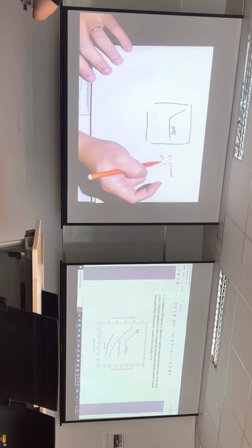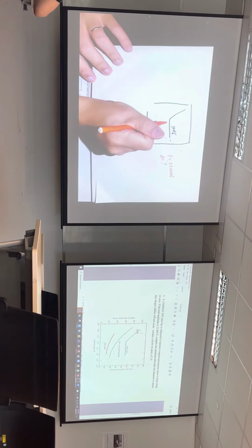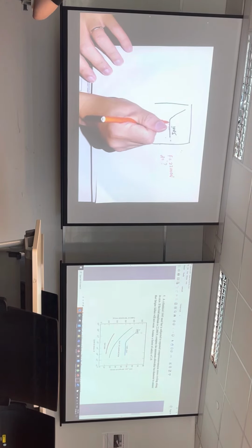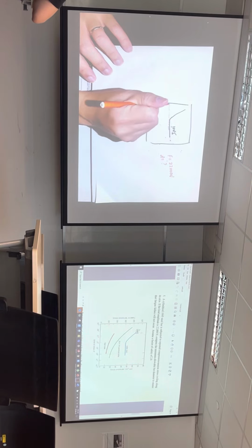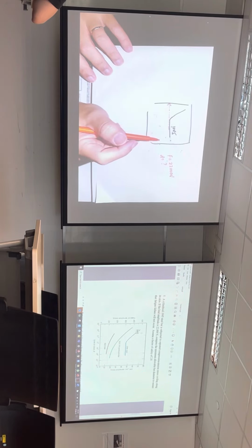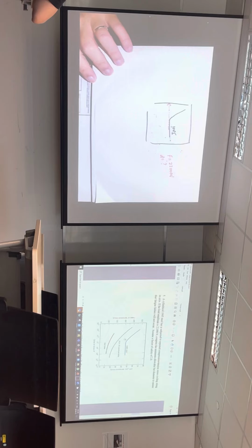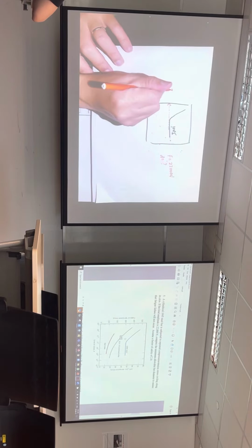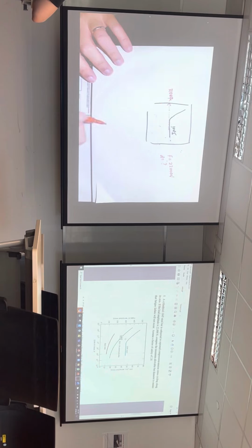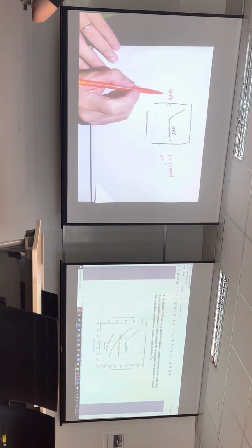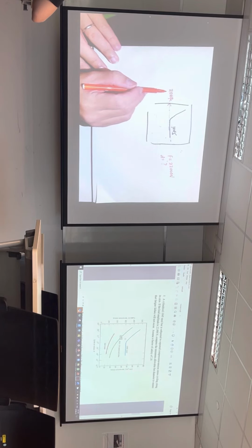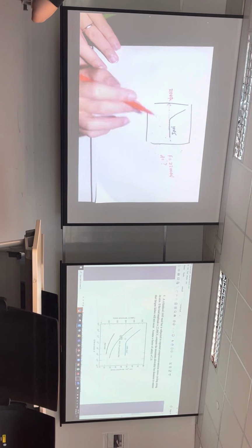So if you want fatigue failure not to occur, then you need to make sure that your stress amplitude does not go above here. The max stress amplitude that you can have will be this particular value. From the graph, this is something like maybe 310 MPa. This is actually the worst case scenario. Anything above this, you will undergo fatigue failure. Anything below, not. And then assume a safety factor of 2. A safety factor of 2 is something I design in to give you that comfort.